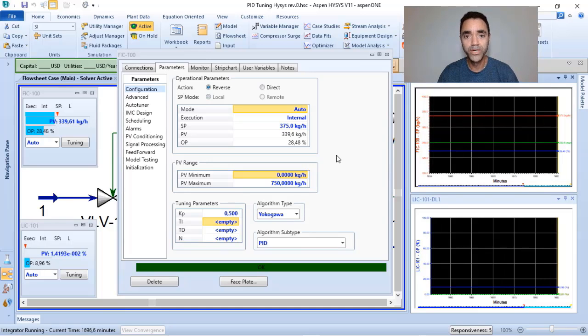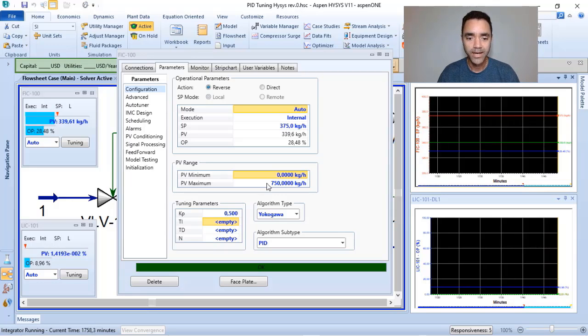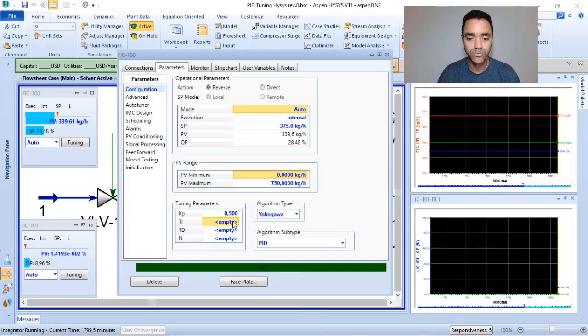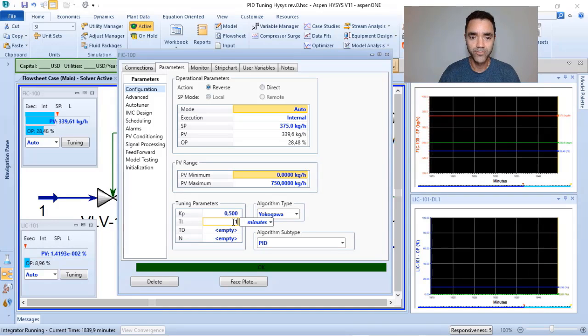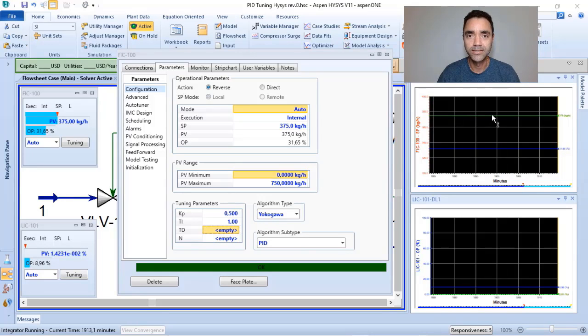So now, to get closer to the set point, I need to introduce the integral value for this process. So here, at first, I will add S1, and let's verify what's happening. Observe that we will have changes in this case only in the flow controller, because I'm dealing only with the flow controller at this time. And now the PV already reached the set point.